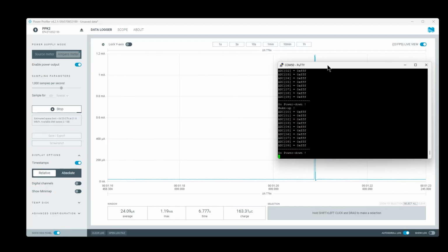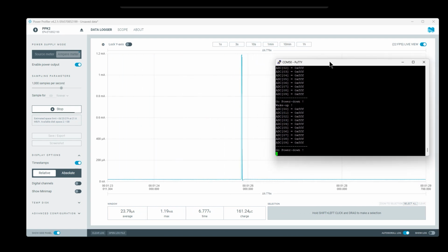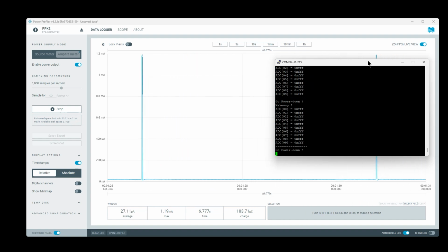Finally, we measured the system's current consumption. From the results, you can see that since the CPU doesn't need to be woken up frequently in this application scenario, the system can stay in power down mode most of the time. The benefit here is that the CPU only wakes up when it really needs to handle a task, and otherwise stays in low power mode to save energy.